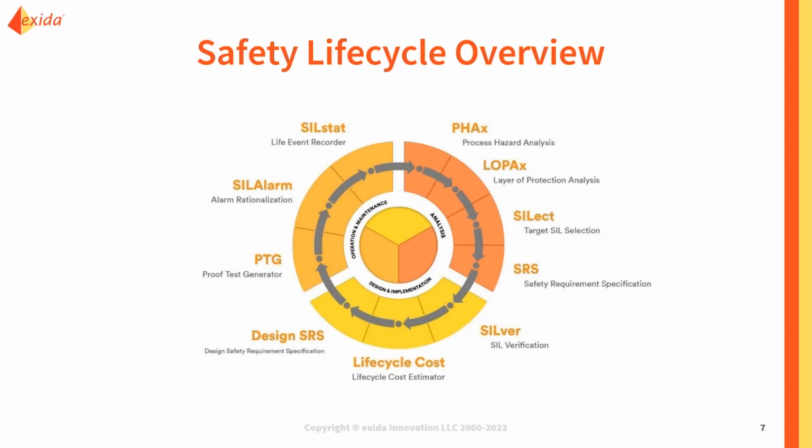And our SILstat tool will help you to collect data during the life of your safety instrumented system as it's online. It's going to help you to keep up with the proof testing that you've specified, record any device failures, any process demands on the system, and see the performance of your safety instrumented system and if it's meeting the assumptions you've made in analysis and design. And so we really do see this as a full life cycle, especially from a data flow perspective.